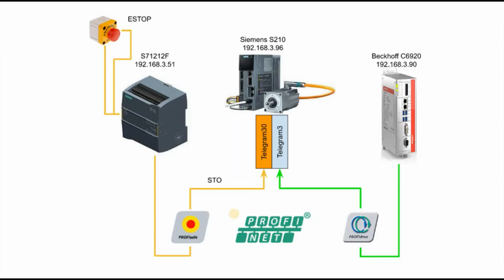Then there is an option in Profinet called shared device. Shared device is a great concept that lets different controllers access the same station but in separate subslots. So let me explain again. Shared device allows different controllers to access the same station but different subslots.